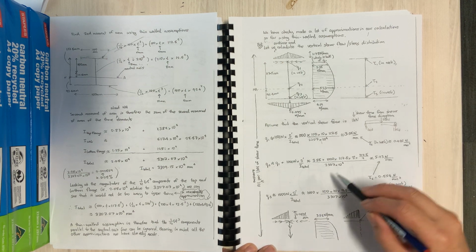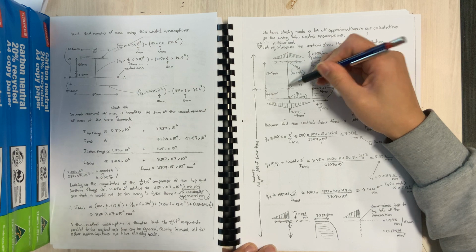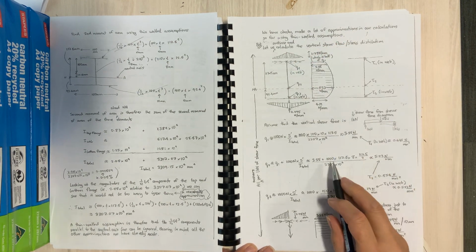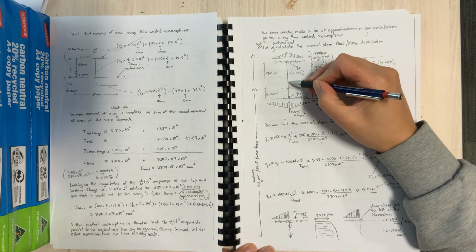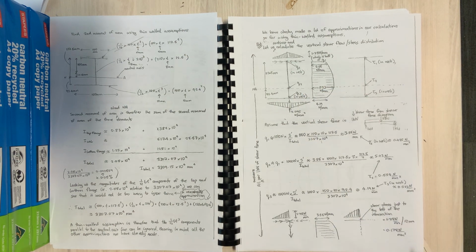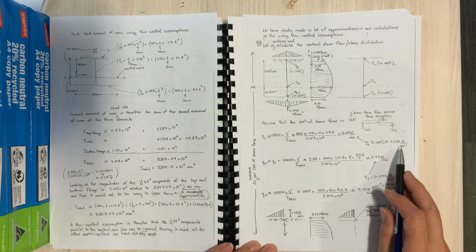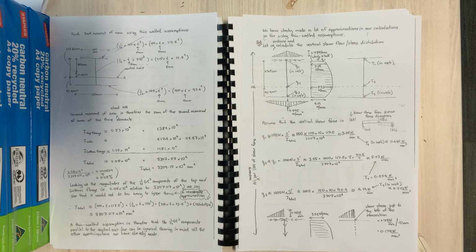And this time here, we're just taking that portion there because we're going to be adding it onto the Q1. So it's going to be that times 8, which is the thickness, times the same distance over 2, divide by I, and we'll get Q2. And obviously, once you've got your Qs, you can turn that into stresses just by dividing by the thickness. So turn it back into a stress if you want.